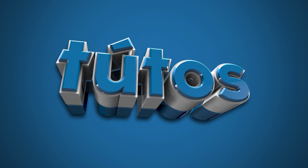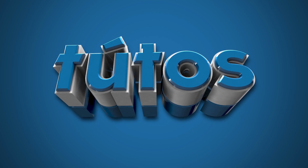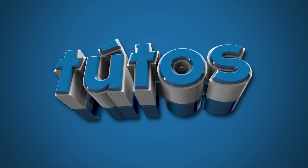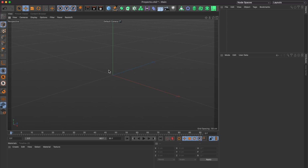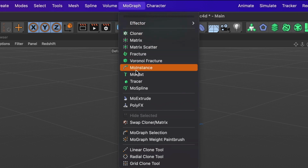In today's video, I will show you how to create this 3D text using Cinema 4D. Let's begin. Once you have your project ready, head over to the MoGraph menu. Inside, go and select MoText.